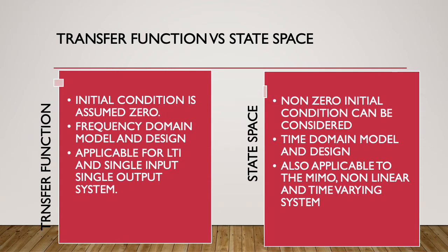The transfer function method has a few disadvantages. The initial condition in a transfer function is always assumed to be 0. It is not possible to consider the initial condition in the case of transfer function design. Transfer function design is all frequency domain design. There is a Laplace transform for defining a transfer function.